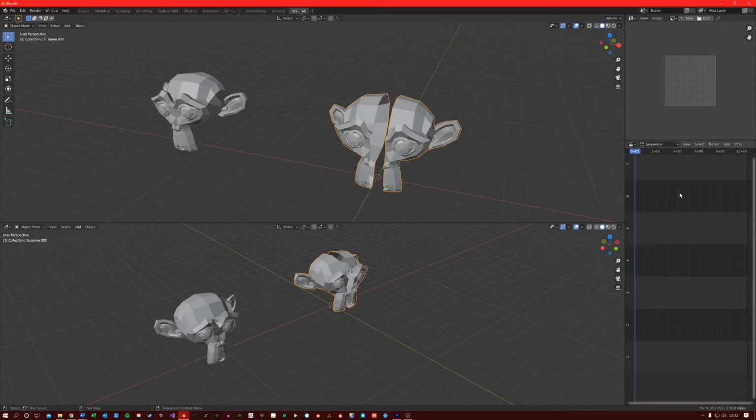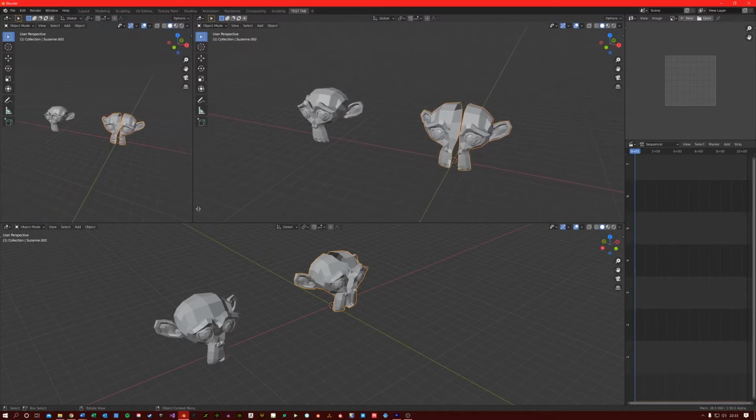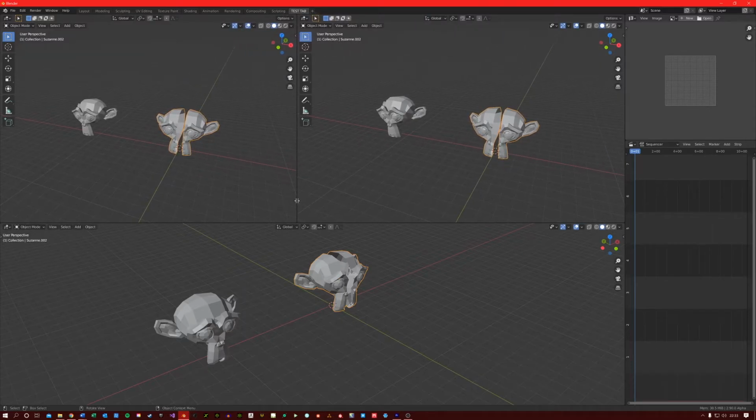But you can do even more than that. What if you wanted to add more sections? For example, what if I wanted to go overkill and have 4 3D viewports? If you go to the corner of the window, you will notice that our mouse cursor becomes a crosshair. And you can do this on any corner. So bottom left, crosshair, top right, crosshair, bottom right, crosshair, etc. With the crosshair showing, if you left click and drag, you will bring out another window. So we could do the same here as well.